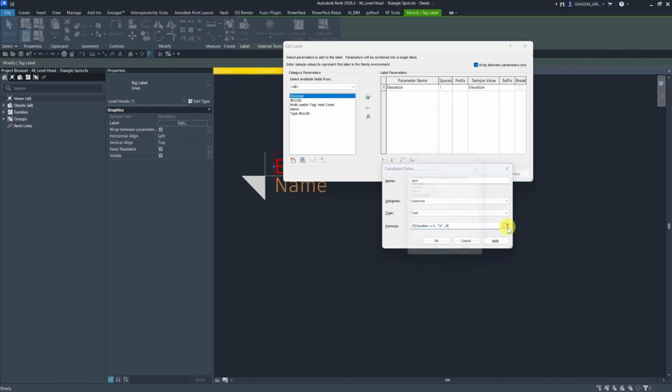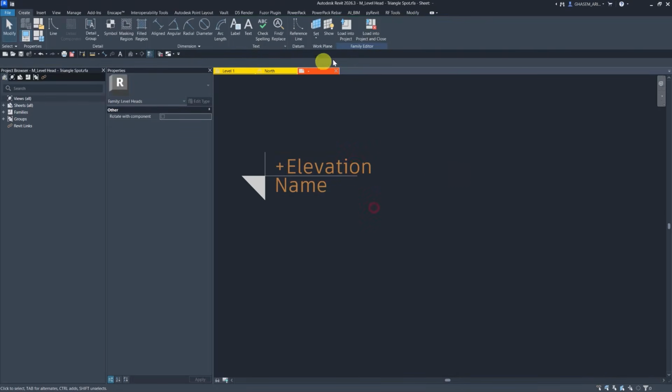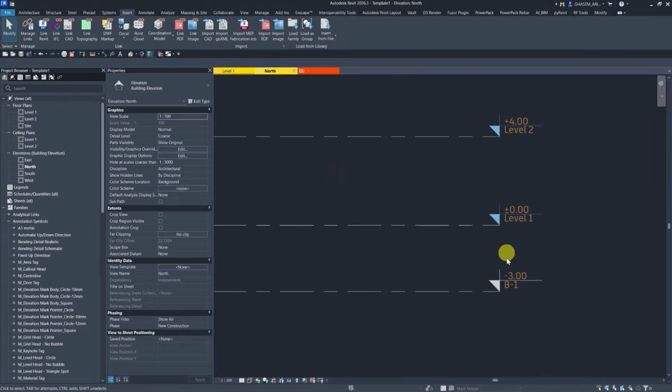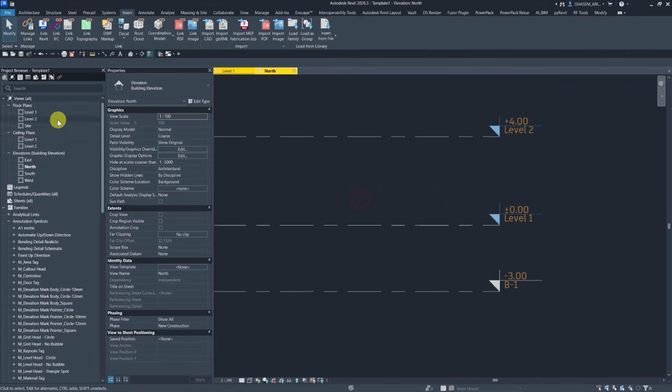All right, now another double quotation. Now one more time, if the elevation this time was greater than 0, give me a plus symbol, and otherwise nothing, null. We've got two open parentheses, close both of them down. Now set this plus symbol here, space and 0. And yeah, I guess that would be it. Let's load this back in. And now as you can see, the mathematical symbols would automatically be added to our levels.